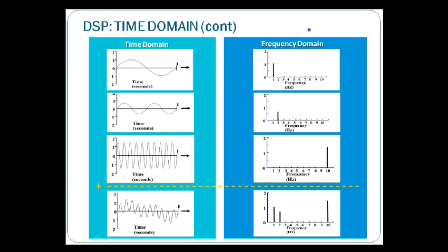All right. So looking into the time domain and frequency domain. Whatever comes in from your DAQ, from your sensor itself, when you are measuring dynamic signals, if you are measuring a very simple harmonic motion, it will just give you one sine wave, as you can see here. From here itself, one cycle in 1 second, immediately you know this is 1 Hertz. Or if you transform it to the frequency domain, then you know that in amplitude over frequency, at 1 Hertz you have one peak at one amplitude, right?